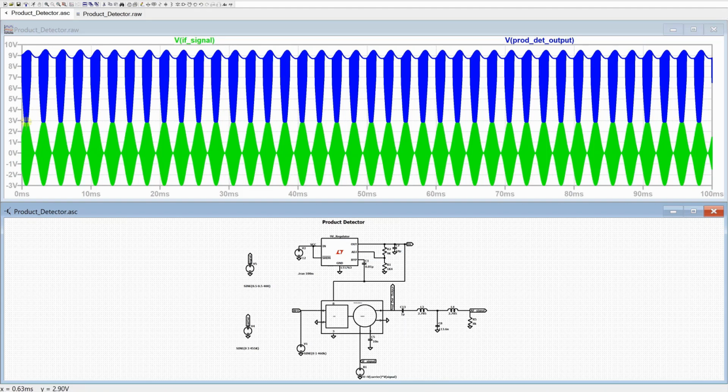So this is the importance of having this low pass filter. This low pass filter is going to allow us to take only the message signal, which is the audio signal, and the carrier frequency, which has a higher frequency, is not going to pass through this low pass filter. So now I'm going to go ahead and take the output from the low pass filter, and we're going to see what we got.